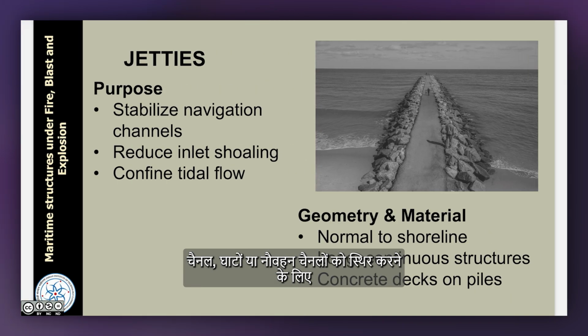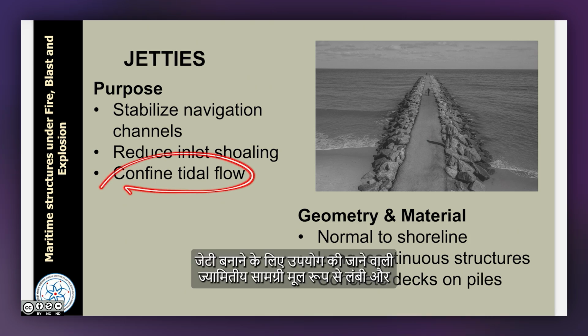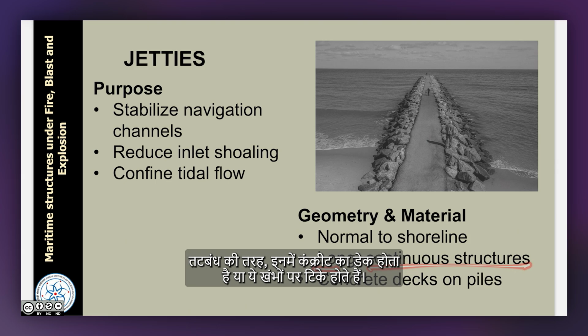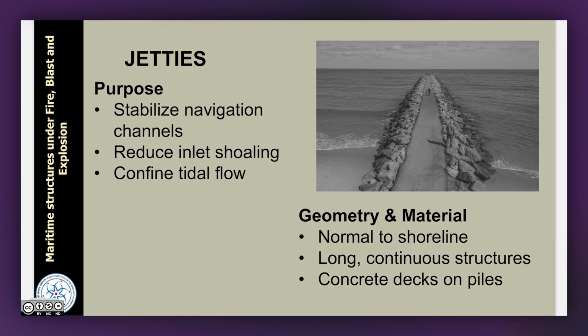Jetties are another structural system constructed for stabilizing navigation channels. It reduces inlet shoaling and confines the tidal flow. The geometry and material used for jetties are essentially such that they are long and continuous like revetments. They have a concrete deck resting on piles. They are constructed normal to the shoreline. Okay. Jetties are mostly permanent structures.